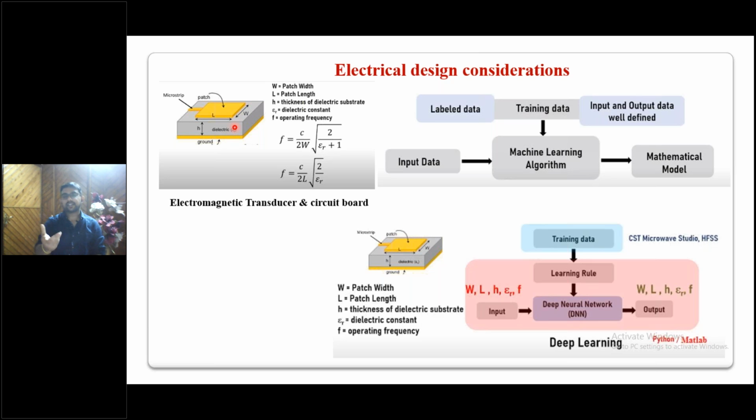Then we'll use a dielectric. Now the selection of this dielectric is very, very important in this case, because your transmission will essentially depend on the dielectric that you select here. If you select a dielectric with less permittivity, then your transmission will be more. You can hold more and more energy. So this is a very important parameter. In normal design for electrical engineering, we use Duroid or Taconic and all these things. Bakelite we also use as a dielectric in normal designs.